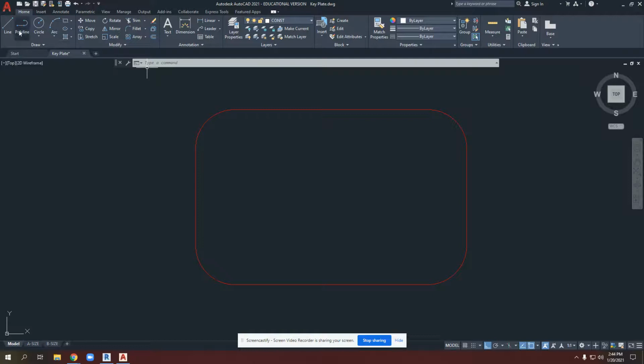So with that construction line, I have a couple of options. I need to find the center of this rectangle. It is relatively common practice, if I still had my square corners, that I could go crosswise from corner to corner, or in this case, fillet center to fillet center. And the intersection point here would be the middle of this object.